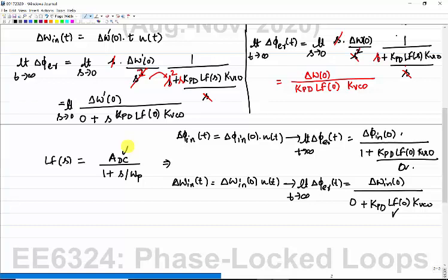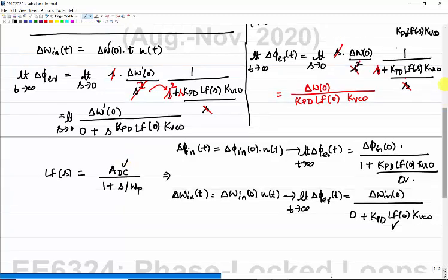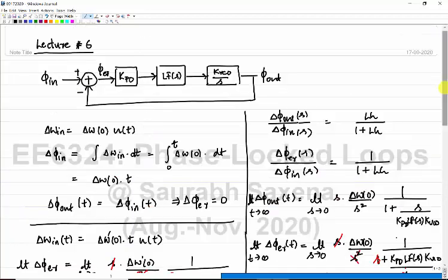Yeah, so the whole thing is I am not that particular about just a delta phi error. I am very much concerned about the absolute value of phi error. Okay, so let us say you keep on changing this delta, right? If the delta phi error turns out to be a large value, how large a value can you have in your system? Looking at the PLL, if you go back, you know this particular phase error detector is implemented by using a mixer, right?